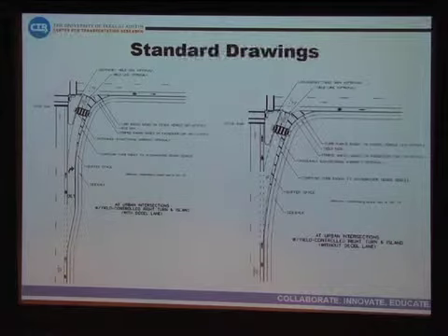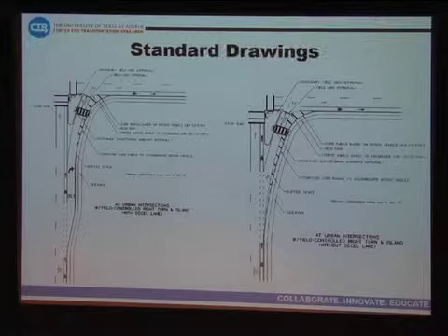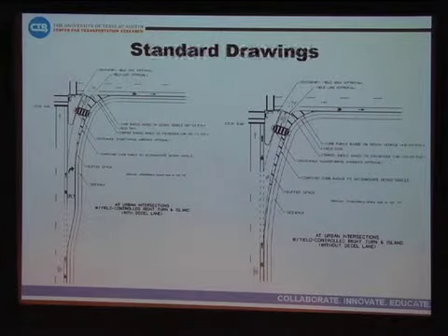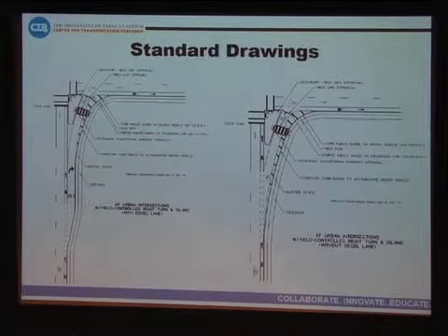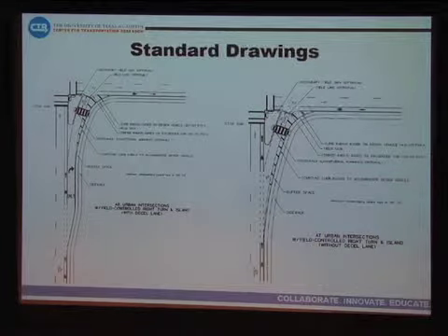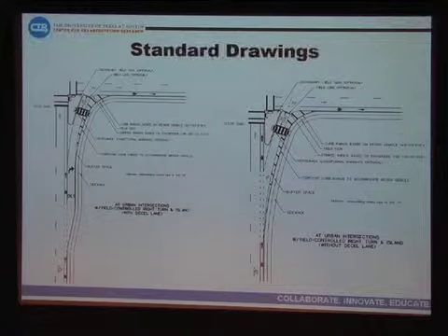These drawings provide some examples of the draft standard drawings to date for these facilities. You see the drawing on the left with the deceleration lane and the one on the right without the deceleration lane. You'll notice a lot of similarities here to the smart channel concept. We've added the longitudinal striping again as a recommendation for the crossing within the turning roadway only. And we're attempting to achieve the benefits of narrowing the turning path for turning smaller vehicles, as well as placing that crosswalk more in the line of sight of approaching motorists here.